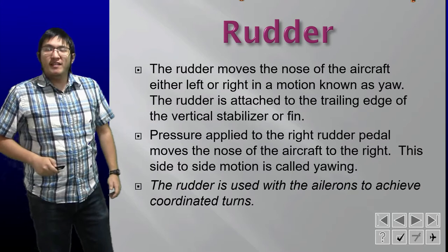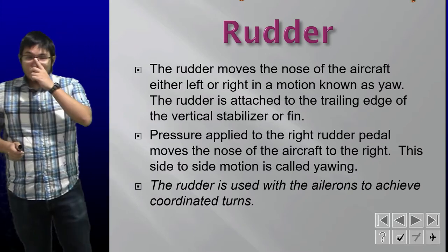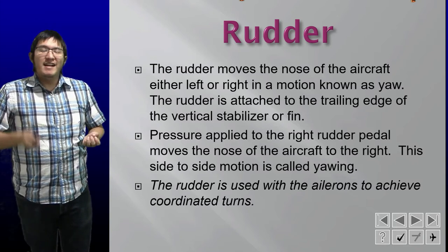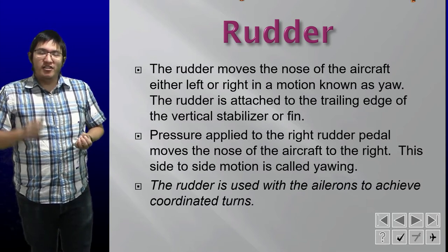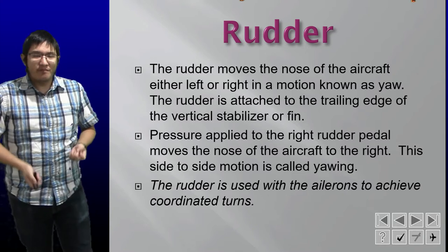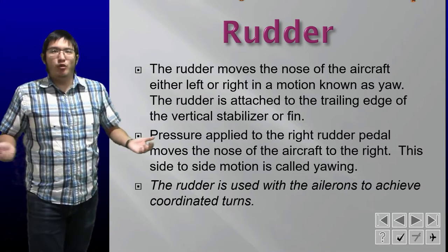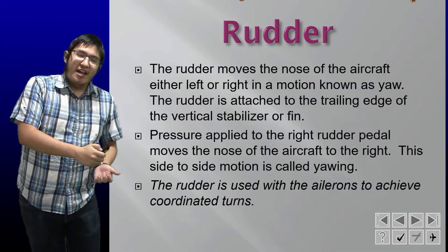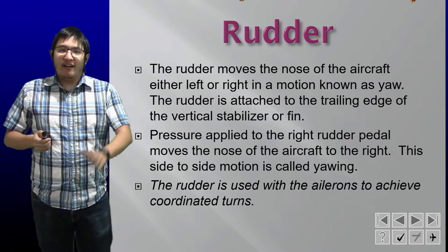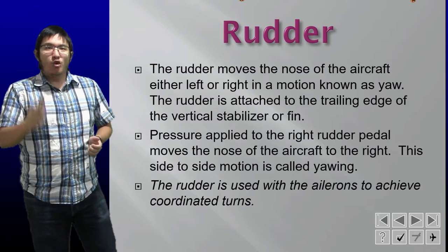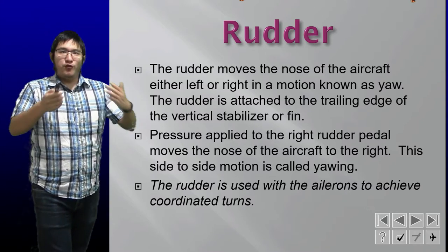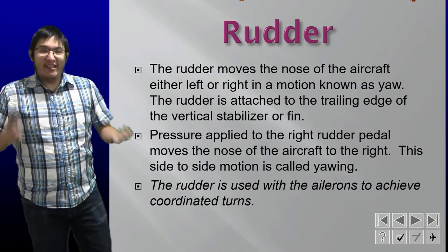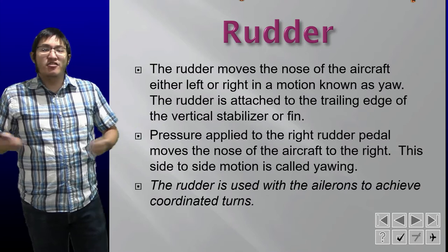This is important, especially when it comes to a glider. Because in a glider, if you don't have coordinated turns, you will tend to drop faster because of increased drag. And in a glider, you really don't want that. So whenever, let's say, we're rolling to the left, we apply a little bit of left rudder in order to keep us coordinated. The coordination ensures that the airflow going over the wings is not coming at an awkward angle, and it maximizes our lifting percentage.